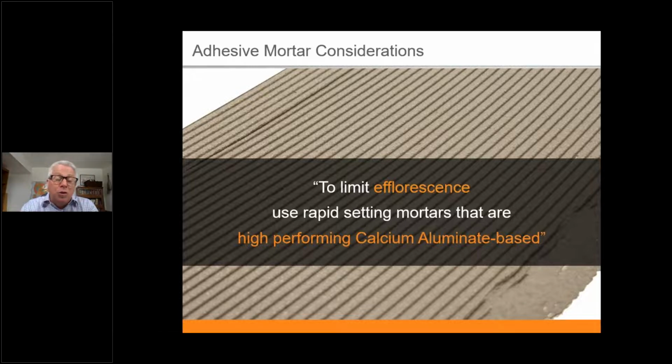In other words, what they're trying to do is eliminate the opportunity for a lot of the free and active calciums or binding salts, the free limes that are so prevalent in Portland cement-based materials, whether it's masonry or tile assemblies. They're trying to minimize the presence of that, which keeps down the amount of that calcium that can actually become free and make its way through the assembly and perhaps even clog up the drainage that you've designed and built into the assembly. So I found that really interesting that this manufacturer said, yeah, let's go towards these.